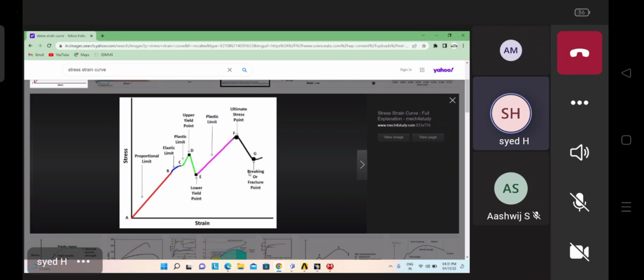Okay, this is my stress curve. But for example, if we have a material like structural steel, for that steel we have to check what is my yield point and what is my ultimate stress point. Why? Because from this ultimate stress point, the object is going to break from here. Like fracture is there from this point only. So that stress value we have to check.